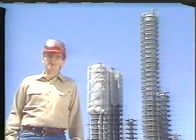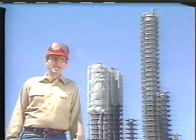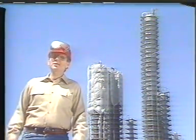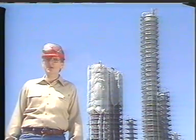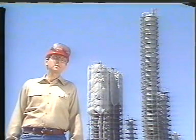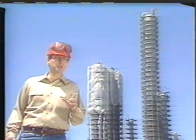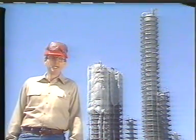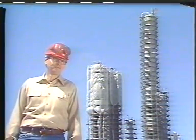Distillation columns are periodically shut down for routine maintenance and inspection. In this section of the program, we'll take a look at some general procedures that are used during shutdown and startup operations. An operator should always read the specific shutdown and startup instructions for his unit before such operations. These procedures will vary from tower to tower and from plant to plant.